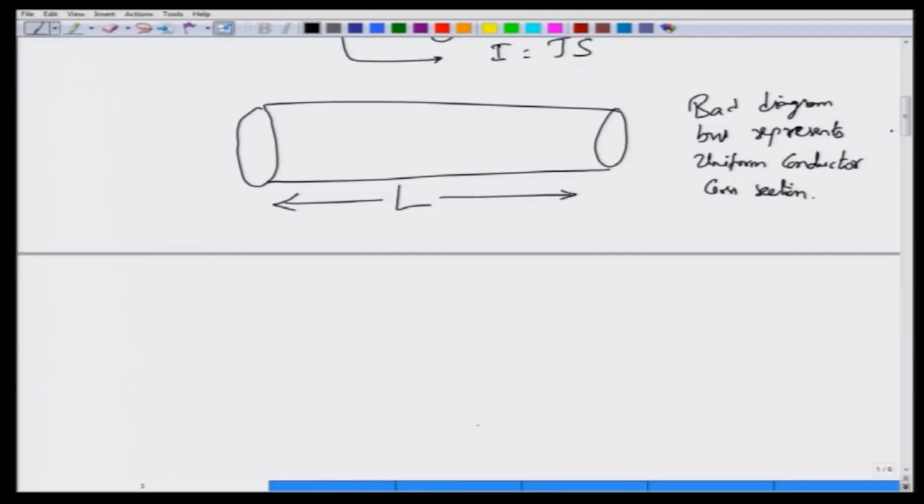So, how do we calculate the voltage difference between the two? If you label these points as point B and point A, the voltage difference between the points A and B is simply the line integral of the electric field inside this conducting material, from point B to point A. You integrate the electric field, assuming dl points along this line from B to A, and whatever you do, you are going to get the corresponding potential difference.